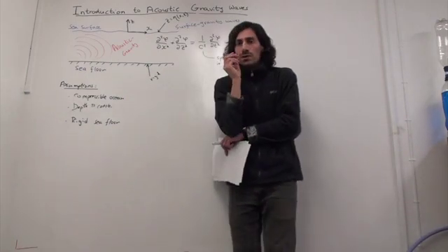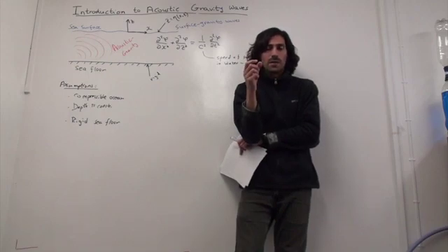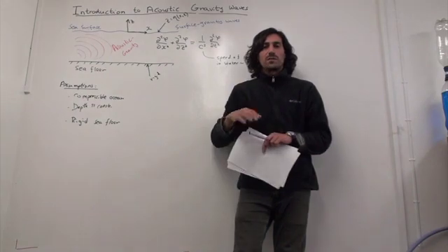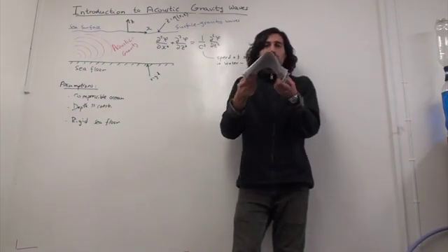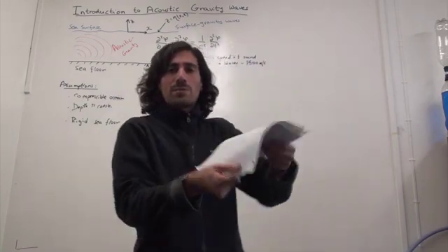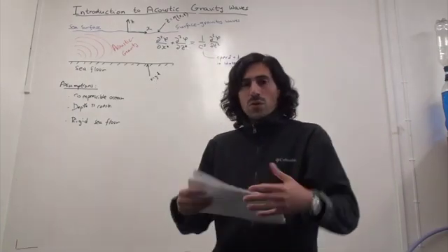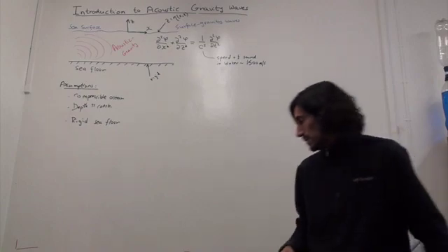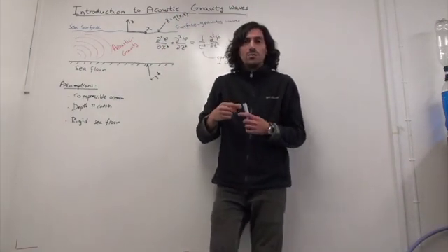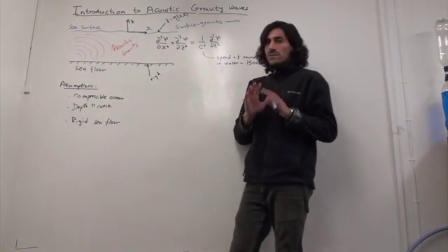What it physically says is that if you have a fluid parcel at the surface, it would remain at the surface forever. In other words, you can think of the ocean as streamlines, and they cannot cross each other. You can have movements, so you can have things like this. These are the streamlines that we have here, with all these nodes. Each one of these is a streamline. You can make all kinds of shapes with it. That would be the waves, but they will never cross each other. So a particle on a streamline would remain on a streamline, and if you have something at the surface, it will never find itself inside in the interior. It will always remain at the surface. This is called the kinematic condition.